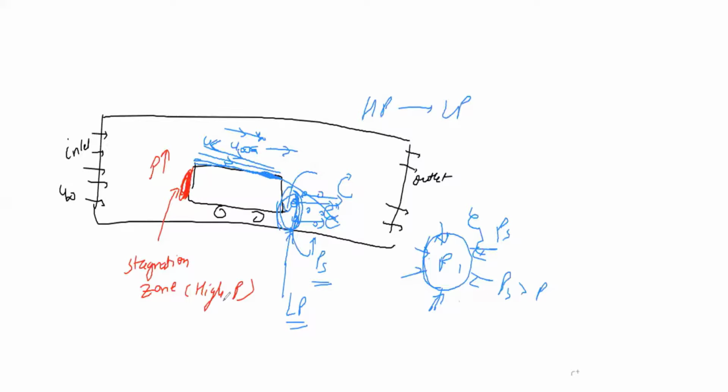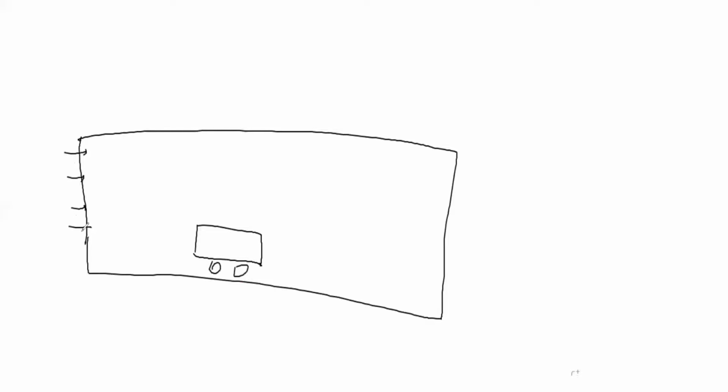Yes, sir. Great. So now the another concept of Y plus which we are going to discuss is this. Why Y plus is very important. See, again I will create a wind tunnel, and again basically I will create a small body. So now you are going to see this is the inlet. You don't need a very fine mesh throughout the wind tunnel. Understand this. You don't want very small boxes throughout the wind tunnel, because anyways we are interested in what? We are interested in the flow physics around the body, correct?